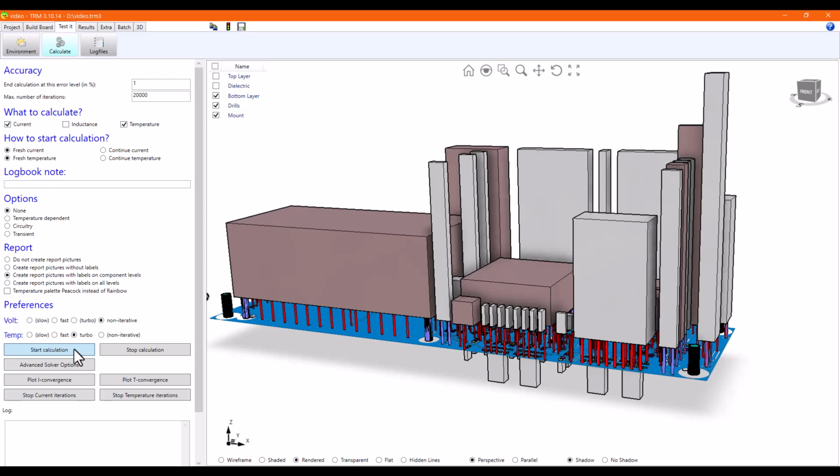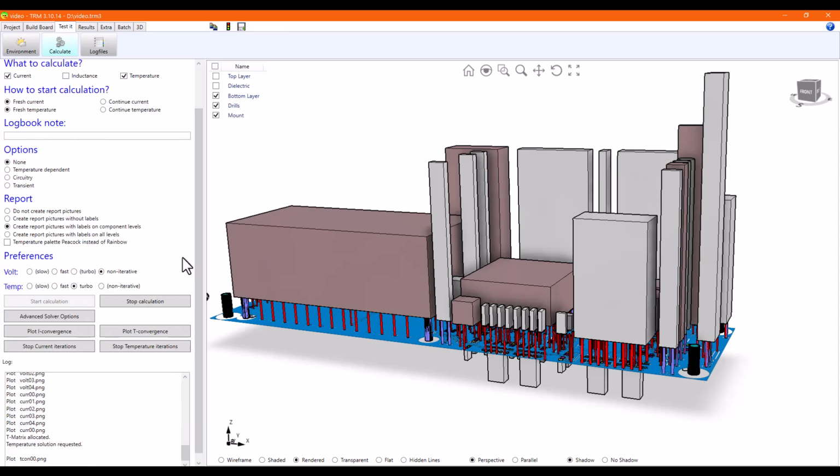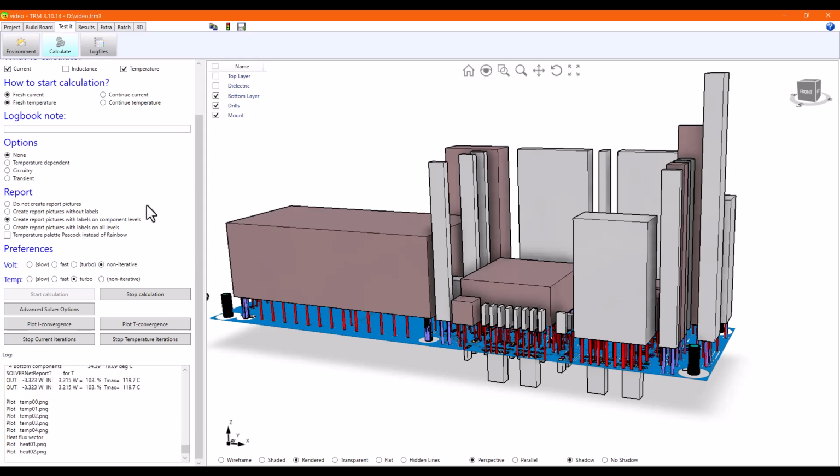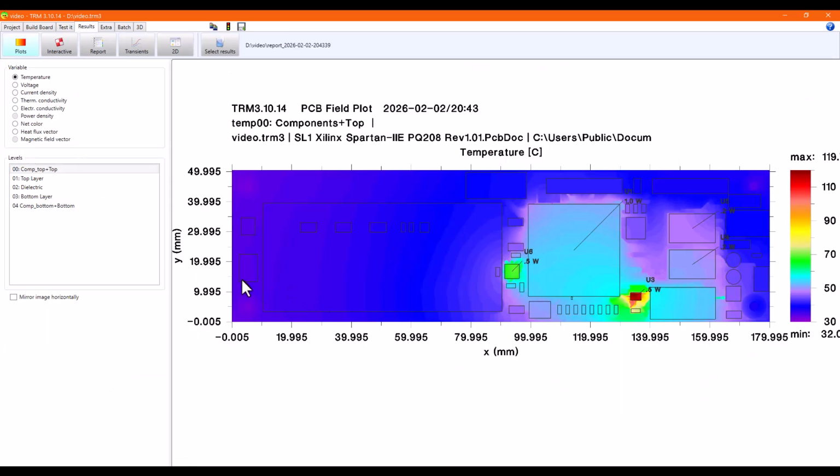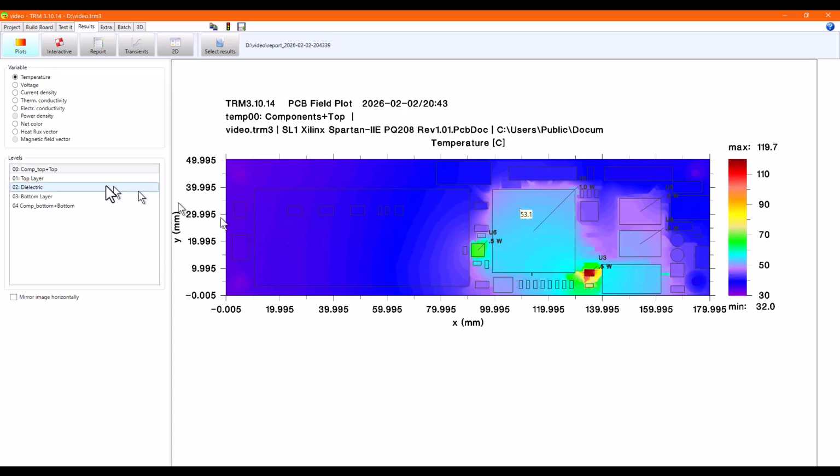It will start calculating the electric potential in our 5-volt net, given by the plus and negative amps. The current density is derived, defining the local power in a net. The power of the nets is combined with the power in the components. Finally, we'll come to a temperature. Now let's watch the results. Those plots come for free. It's not necessary to do extensive post-processing.